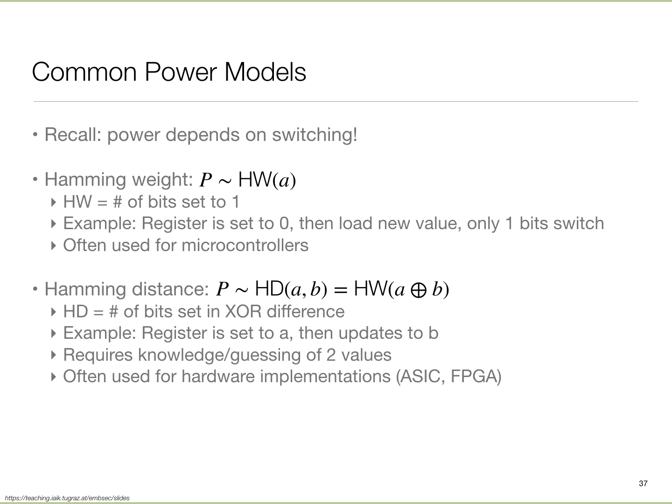Exactly, right? If you add a capacitor, it's like a temporary charge storage. So I smooth out the signals, basically a low pass filter. All these spikes and all that you're seeing will just be smoothed out, right? So you can put a big capacitor, and then the external one is smoothed out and I'm safe. Okay, so that's a board level solution, and a reasonable board level solution.